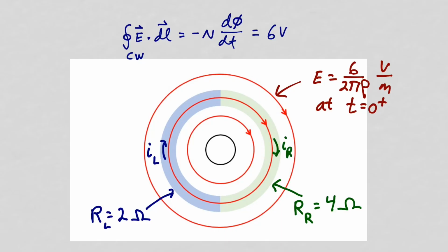So at the boundary between the left and right rings at the top, there's more current flowing into the boundary than away from the boundary, so it will start to charge up positively. At the boundary on the bottom, there's more current flowing away from that boundary than into that boundary, so there will be a net buildup of negative charge. This charge buildup will result in additional electric fields emanating from the positive charges at the top boundary and terminating on the negative charges at the bottom boundary.